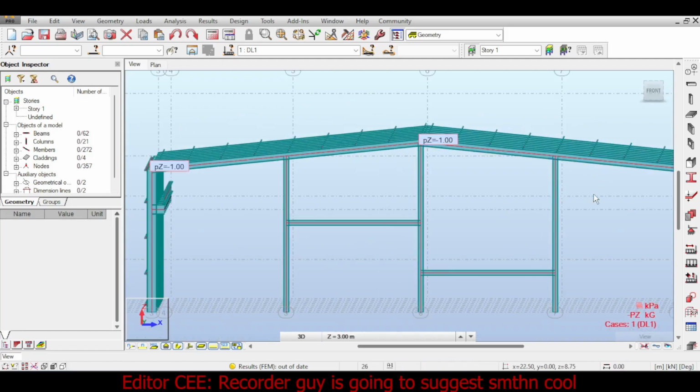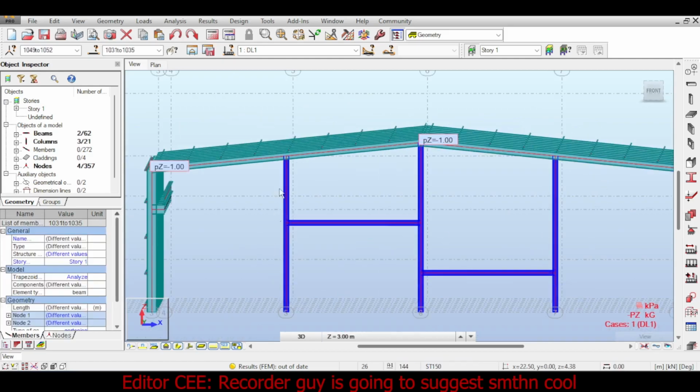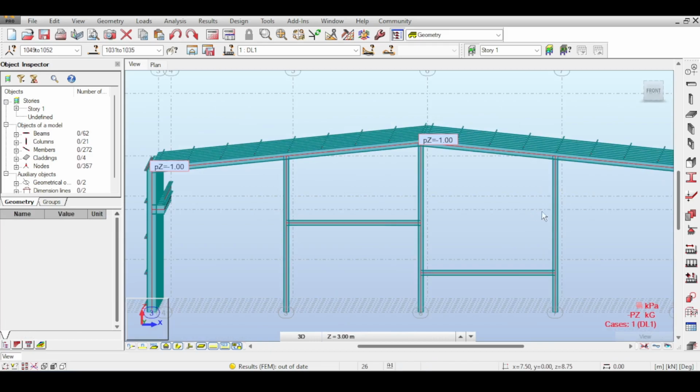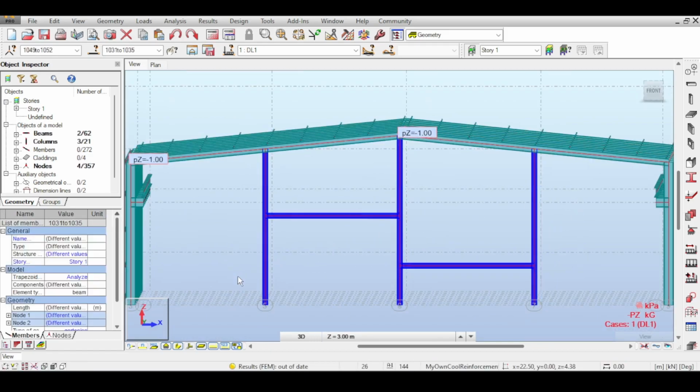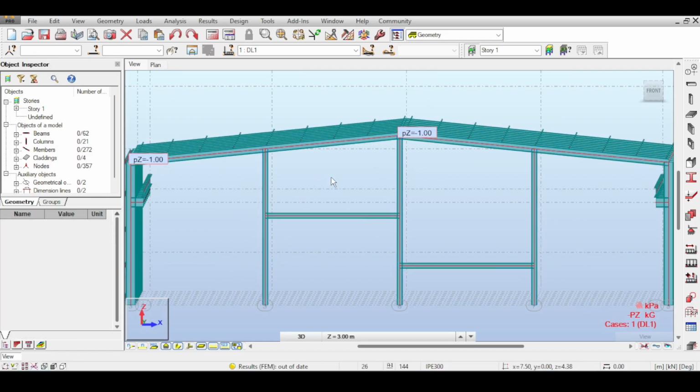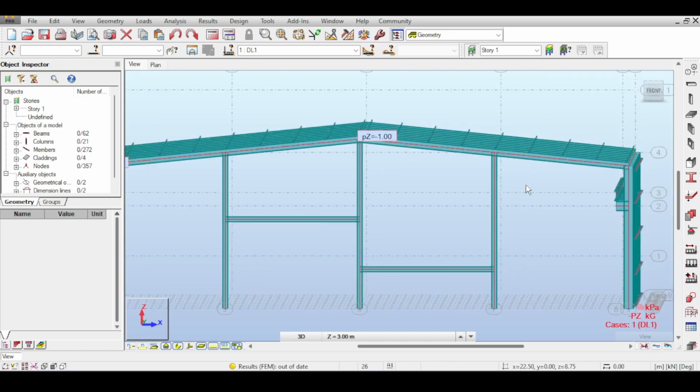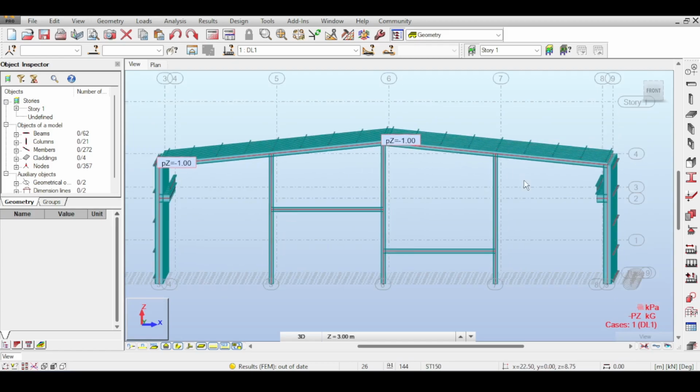Option one is to consider the gable frame not touching the portal frame, because this allows extension, so you can delete the gable frame in the future and extend the portal frame. Or the other option was to allow the gable frame to carry the portal frame, and then the portal frame gets smaller. Or in case you want a third option, here's my thoughts on that.